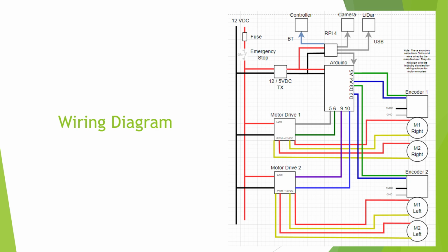There's some mapping between the rotation and the encoder count, and usually it's quite high, so you get fairly precise measurements of the wheel rotation, depending on the motor and how you set up the wheel diameters. You get feedback on the motor turns, and through that, you can get some sort of estimate of your position. That's kind of your global position. So using the LiDAR and the wheel encoders, you can get position.